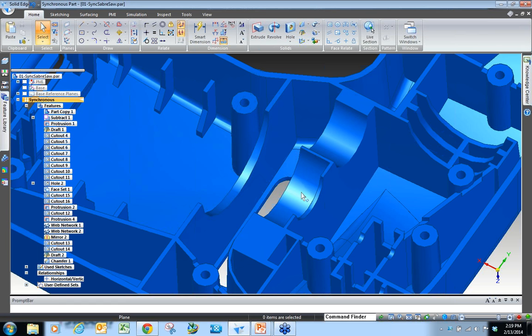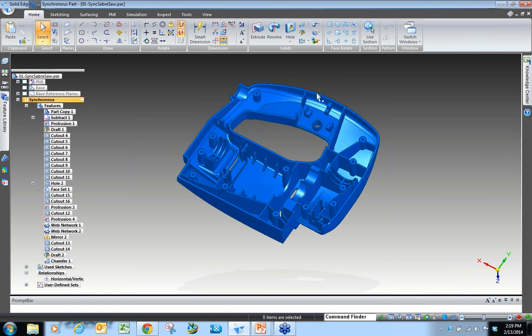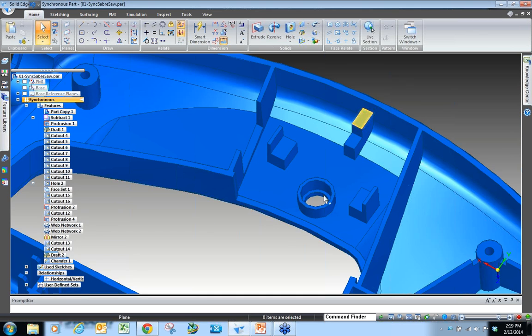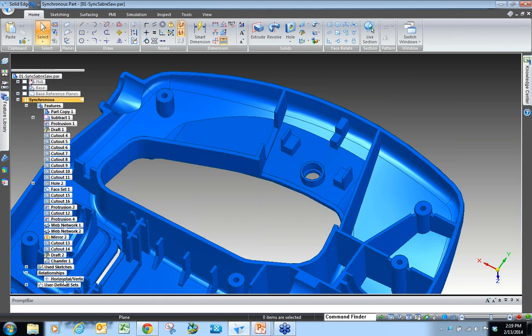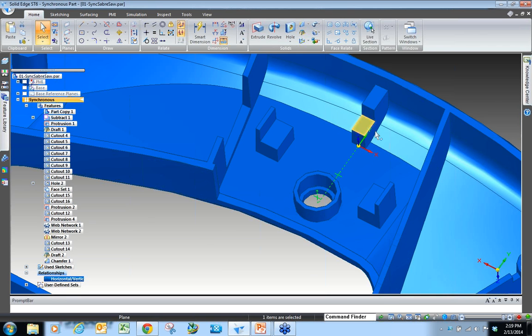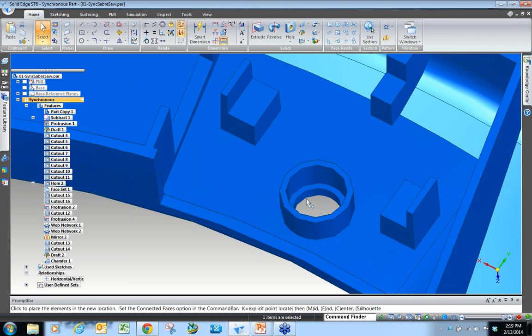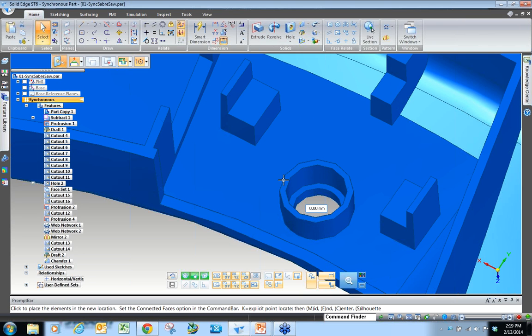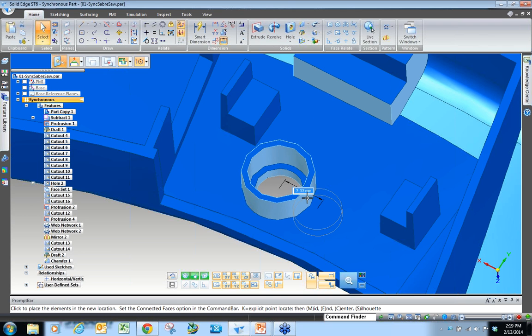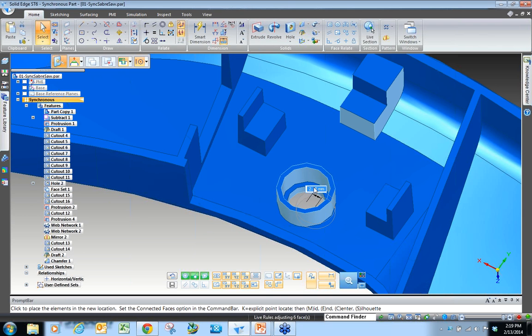We'll go ahead and it allows me to make the change. Same thing if I look over here on this top part. If I go down here, I'll look to see I have a horizontal vertical relationship between the center of this part and the outside of this area here. If I click and drag and move this part around, say I want to move it over to the side, you see how the little top tab goes ahead and moves around too.